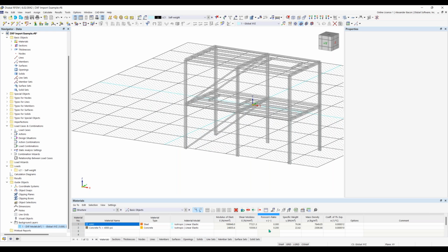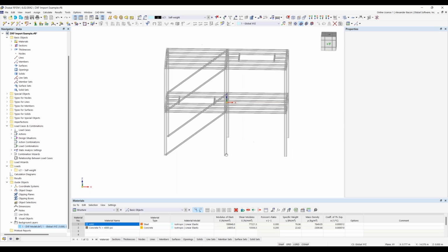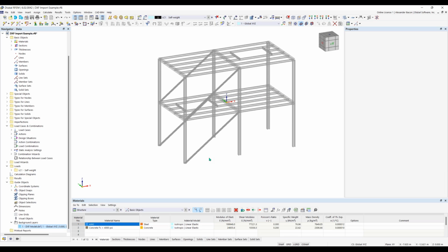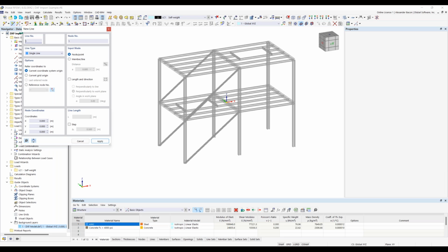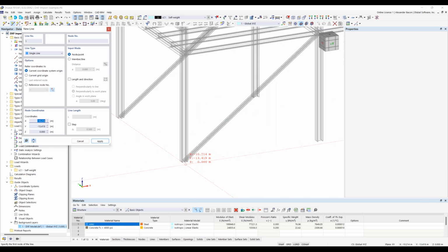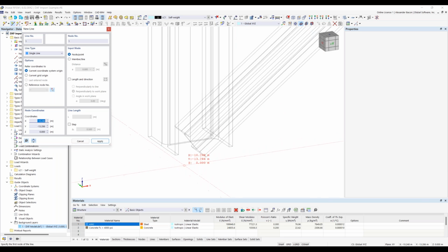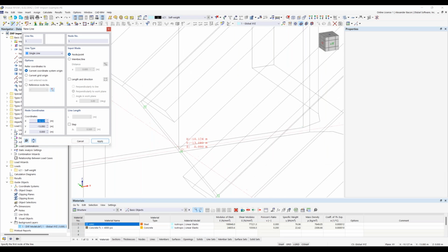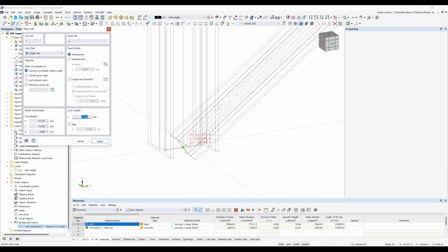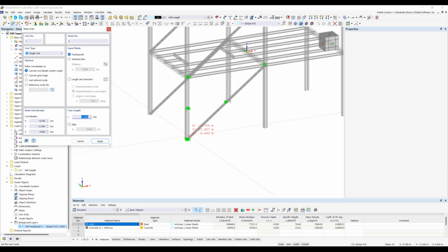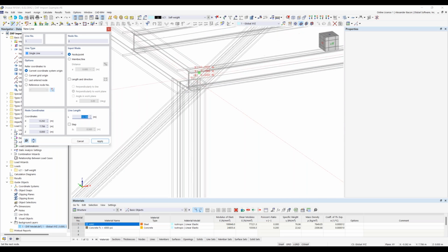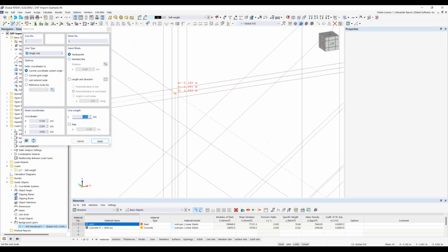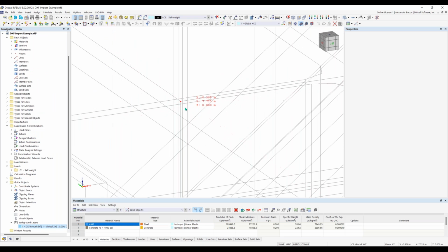So now we can use these background layers to model this. This is similar logic to the IFC file that I showed. And I'll just do an example real quick. So we can draw a line, a center line again. I'm going to use this column again as an example, so I can zoom in here and snap to this point if you have your object snap settings turned on. And then I'm going to go to the top here and I can snap to this point, right click,